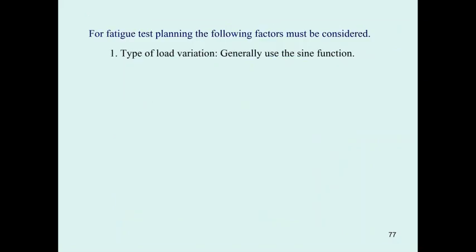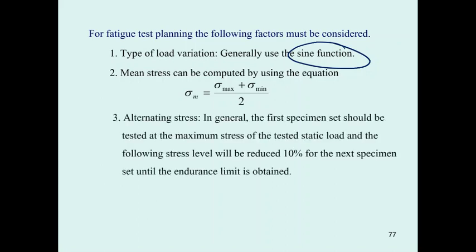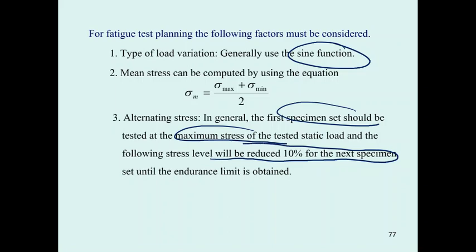For fatigue test planning, you have to consider the type of loading variation. Usually the load is a sine function, as the one we have in our lab. The mean stress is computed by this equation. In our testing, in general, the first specimen set should be tested with maximum stress, usually going down by 10% for the next.